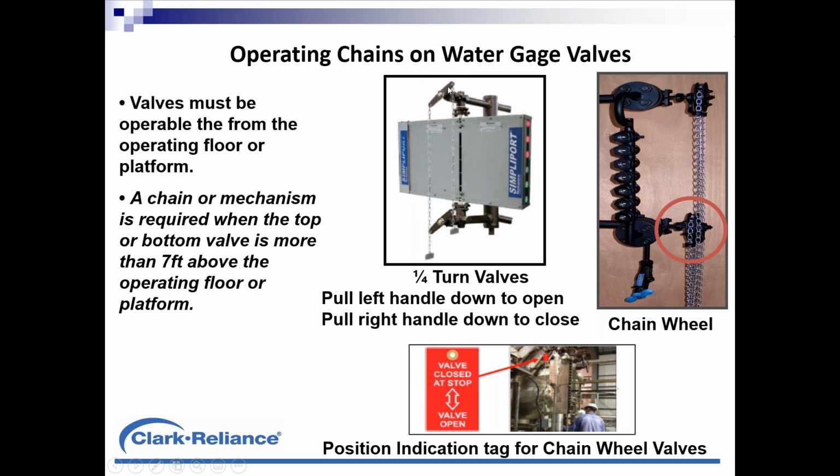So when properly instructed on these valves, when I see the right hand at this lever at about a 2 o'clock position, the valve's open. When it's at about a 5 o'clock position, the valve would be closed. When you have chain wheel valves, they're typically installed on single pitch thread valves. So those wheels probably have to spin 2, 3.5 times perhaps for that valve to be either fully closed or fully open. To be properly installed, these valves must have independent chains for each wheel.